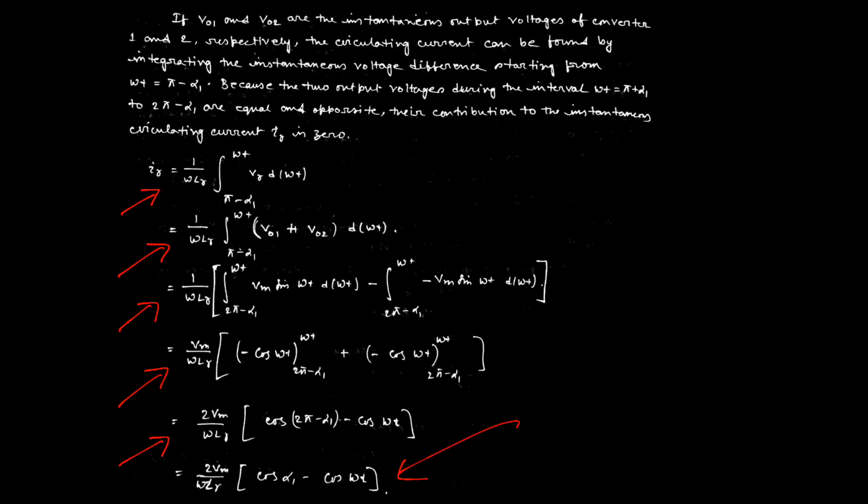If alpha 1 varies, suppose, from 180 degrees into the next cycle, then the second converter can provide the negative current. In this way we can adjust alpha 1, by which we control the converter output across the load, that is across the motor. Then we can easily control both the direction and the speed of the motor.